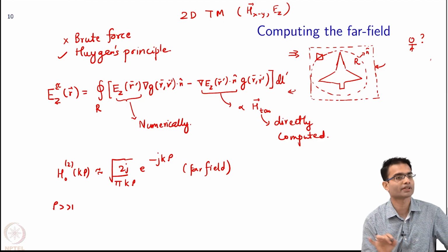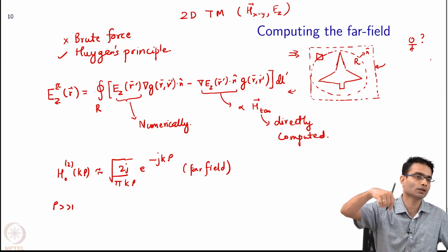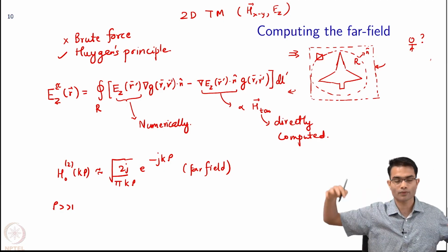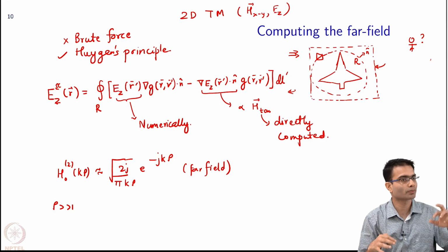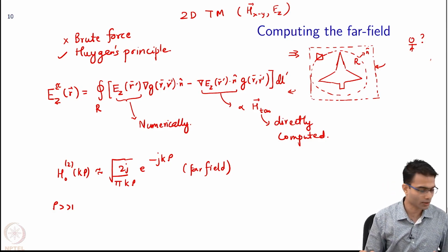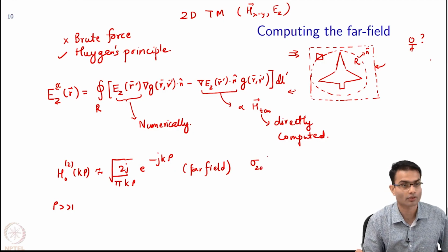So now I know everything inside this. So numerically I have to take the numerical curl of H. That is why it is important for my mesh to be very fine, so that the numerical approximation is more or less correct.